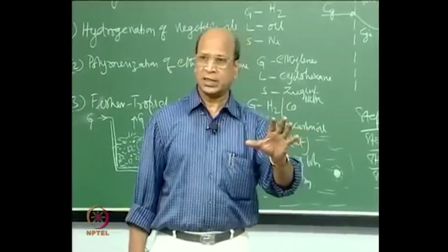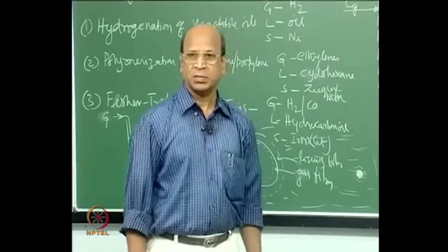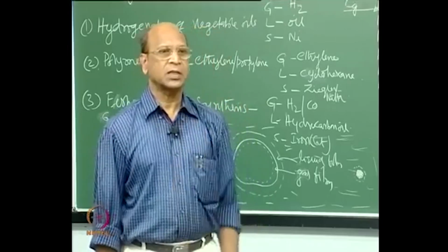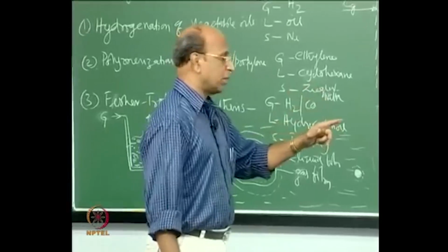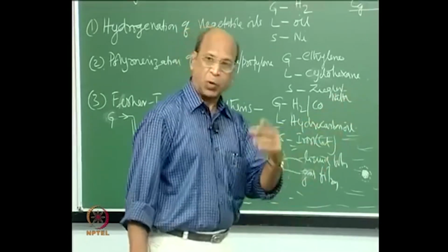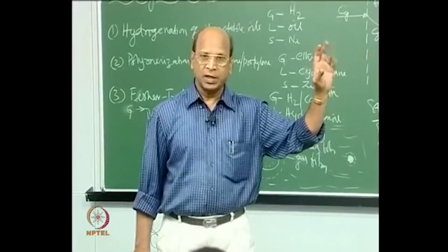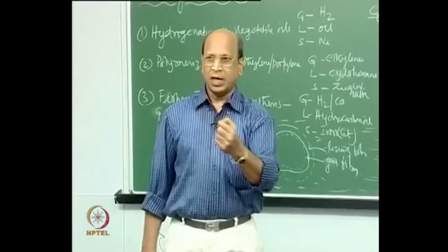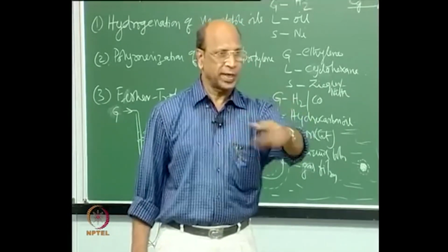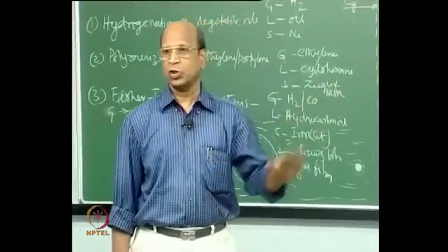So that is why, in entire heterogeneous engineering, even though we have not done the details of how to find out, for example, mass transfer coefficients, the beauty in heterogeneous systems is there will be 6 or 7 mass transfer steps and only one reaction step. So all the time our duty is to find out mass transfer coefficients, and if there is a problem with heat transfer, also heat transfer coefficients. Here we do not have to worry about heat transfer, because isothermality is maintained inside the particle, since they are small particles, and also inside the liquid, because I have a large amount of liquid where all the heat is absorbed and the liquid is moving very vigorously. So uniformly the heat is distributed in the liquid, you will get isothermal temperature.